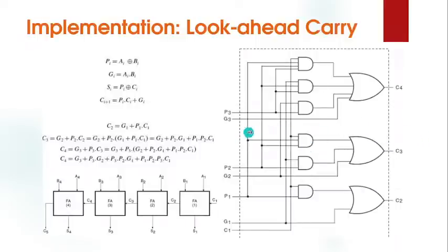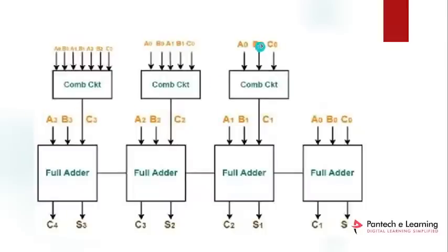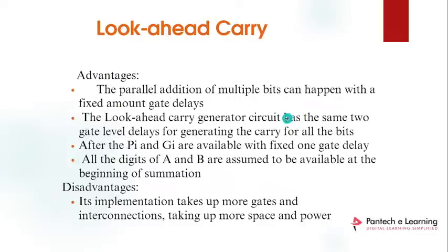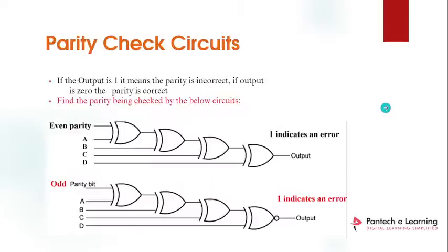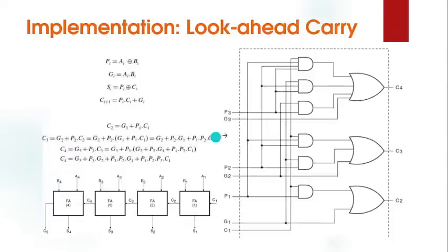You can refer from this. This is the logic. I will show you. You can see here the input of the common circuit having A0, B0, C0 that are given to here only. Like this is one common circuit, this is another common circuit. By using these circuits, we get the correct results or delay free results. This is the main advantage of the carry look ahead adder.